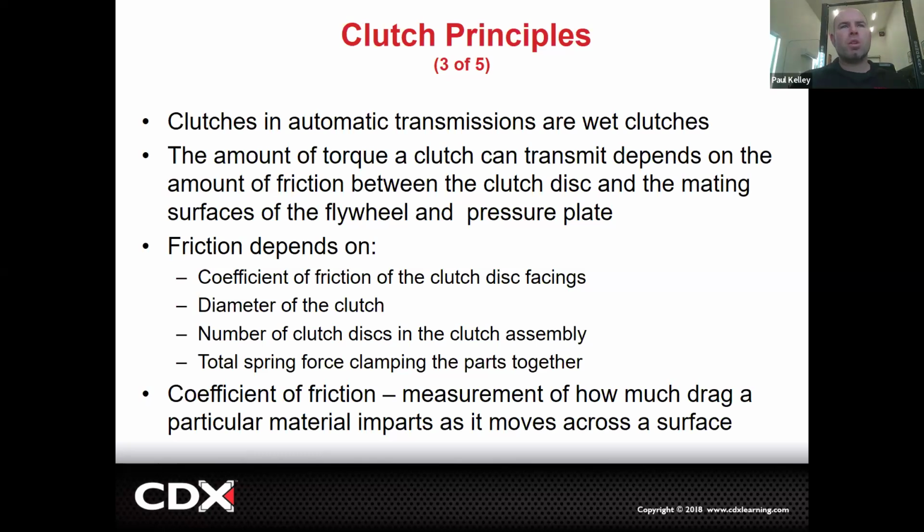The best thing that you can do to make a clutch last longer is not slip it. So if you're coming to a stop, stab that clutch pedal quick, disengage it right away. And probably more critically, when you're taking off from a stop, the faster you let the clutch pedal out, the less you're slipping the clutch, the less it's wearing, right? So in a way, if this pressure plate spring is really strong and it causes you to basically go from the clutch disengaged to bang, the clutch engaged, it would most likely prolong the life of the lining material.